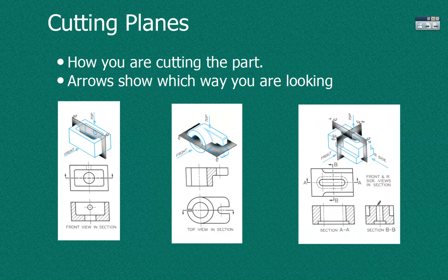In Fusion, or Inventor, we're not going to be able to do this setup and have these two be lined up. If we did section BB here, it would create section BB right here. We might be able to rotate it and move it down, but just putting it here is still acceptable, right? So just leave it there. Doing it by hand, you can draw it over here, whatever. But if you're using a computer and it creates it here, just leave it there. It's not worth it to try and rotate it, move it down, and get it realigned.